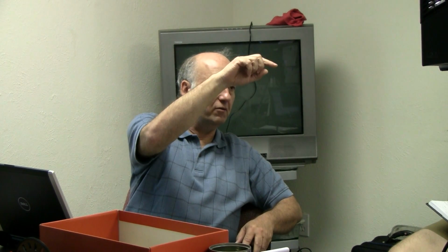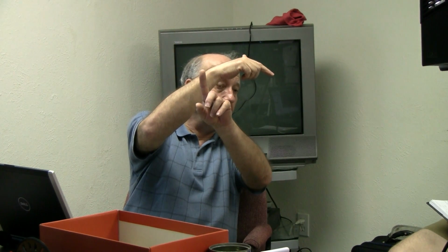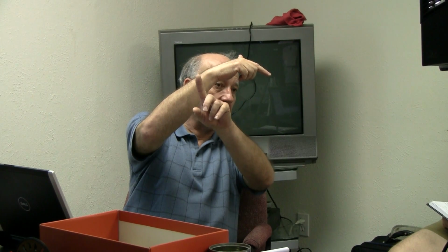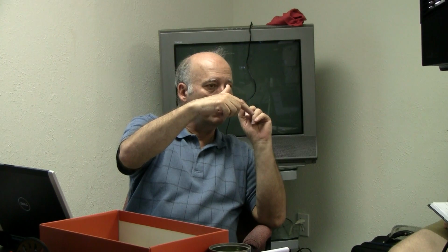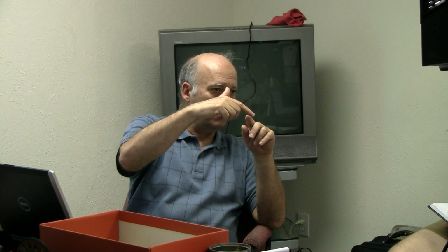So you go to one end of the rat's nest line, change your level to the backside copper, click, and drag your trace to a place where you're going to want to do the jumper. You hit V, you'll create a via there, and you'll notice that it also changes the level automatically to the front level. You go over to make your crossover over the green line that you were trying to get around. You hit another via, and it will place a via there.